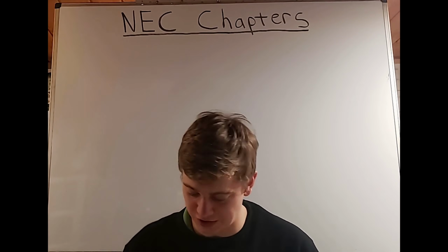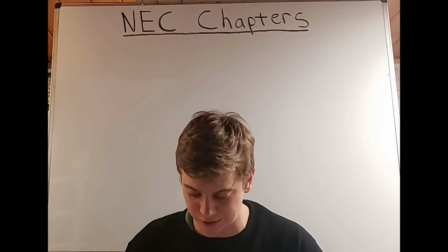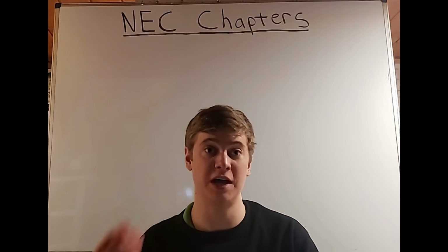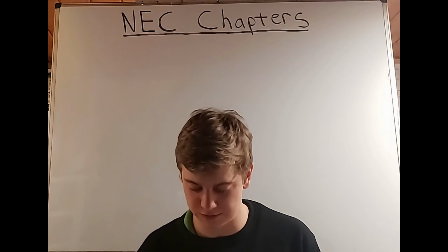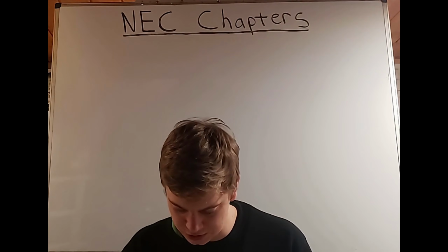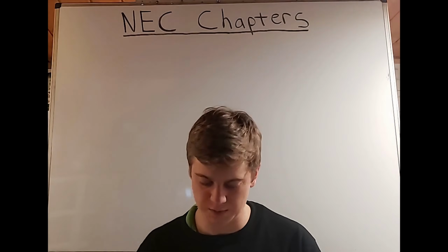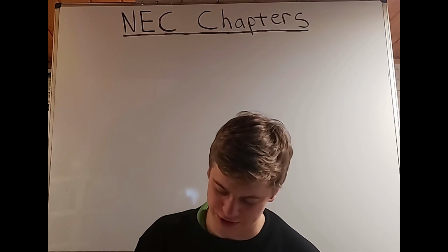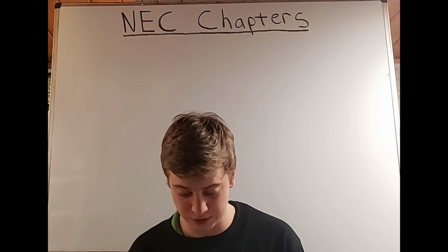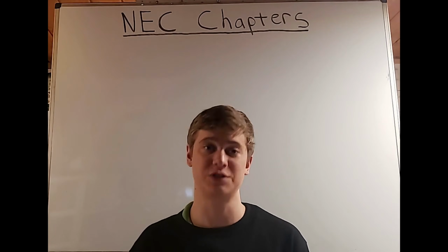We see number 2 talks about mines and self-propelled mobile surface mining machinery, which are of course installations underground, which include the electrical cable needed for that. 3 and not covered mentions railways for generation, transformation, energy storage, transmission, or distribution of power. And then we see number 4 mentions the installation of communication equipment under the exclusive control of communication utilities located outdoors or in building spaces used exclusively for such installations.